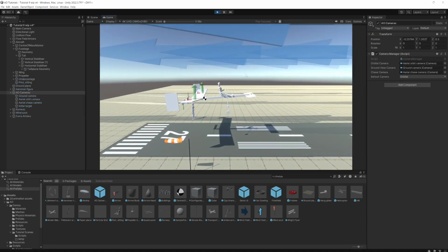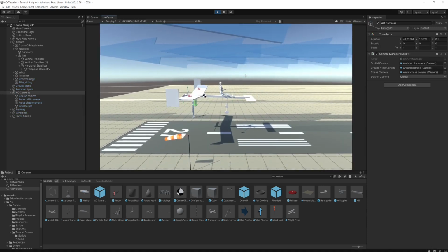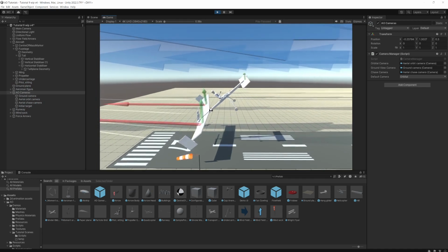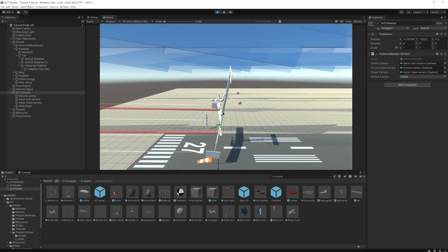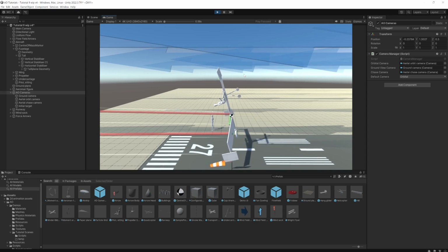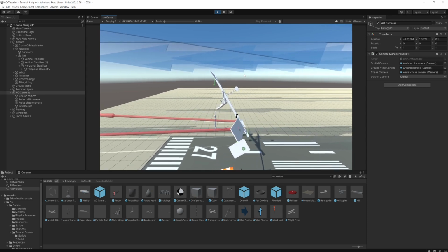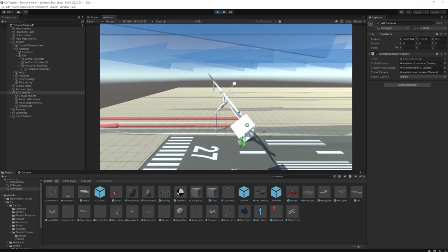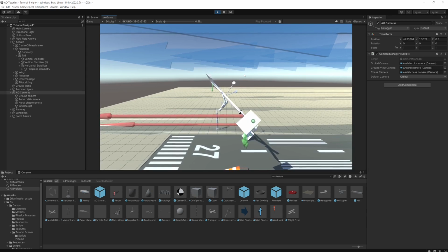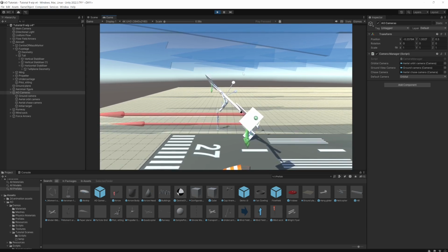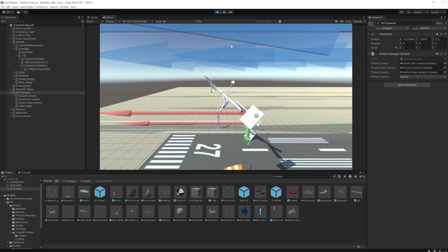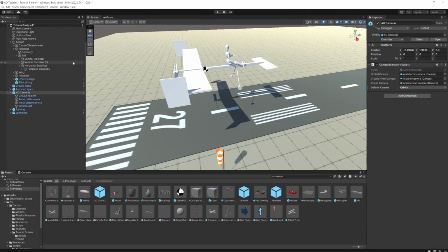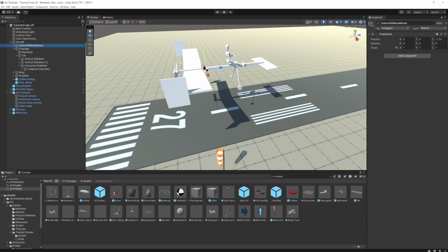immediately pitched up, and I can just about control it if I'm doing some very active control. Well, I lost it there. It's gone unstable. So if we had a flight control system on there, probably the aircraft would be just about flyable, but just by a human pilot on the keyboard, that's too unstable. So what we've seen there is that the centre of gravity is too far back, so let's just move it forward to about where it was before.